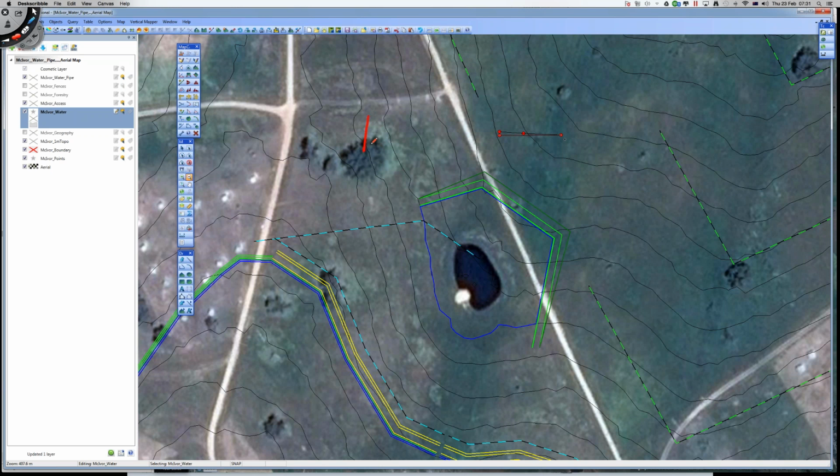All right, so 1:1 is not that; it's 1:1. So 1 meter of depth or length for 1 meter of height. So that it's also 45 degrees or 50%. Right, that is 1:1. Most earth moving uses the ratios as opposed to percentages or degrees. So anyway, let's say we want to do that.